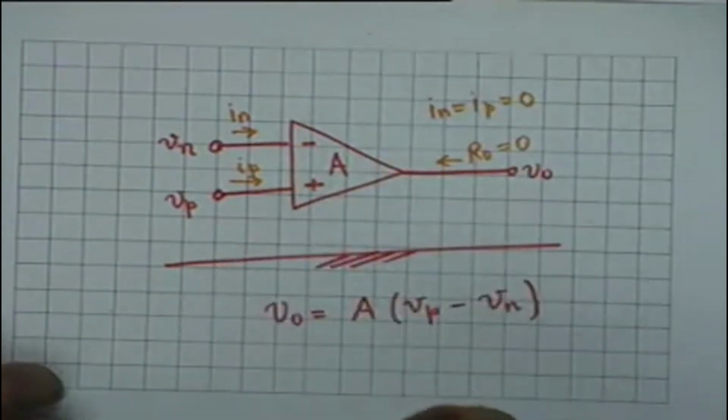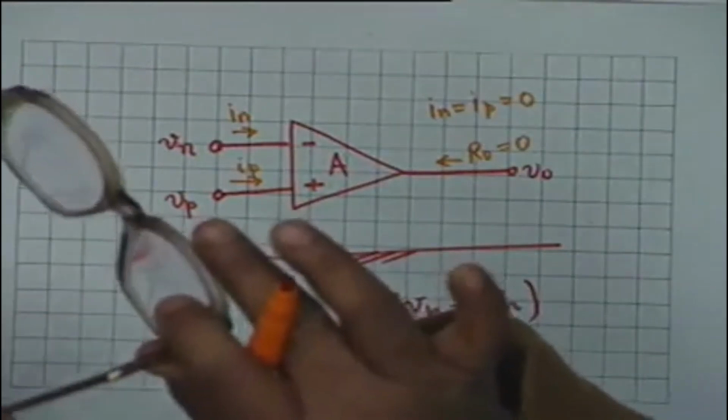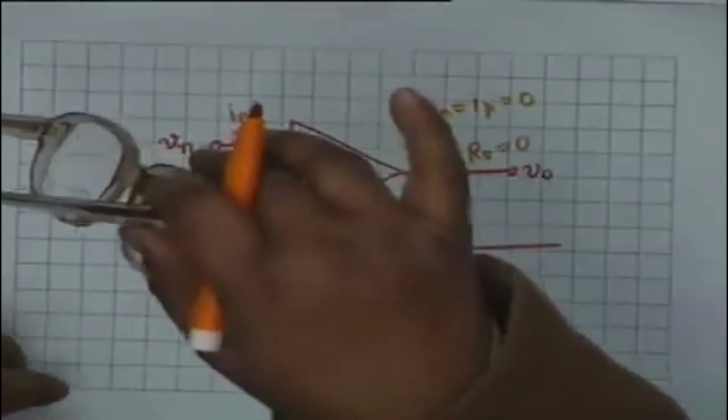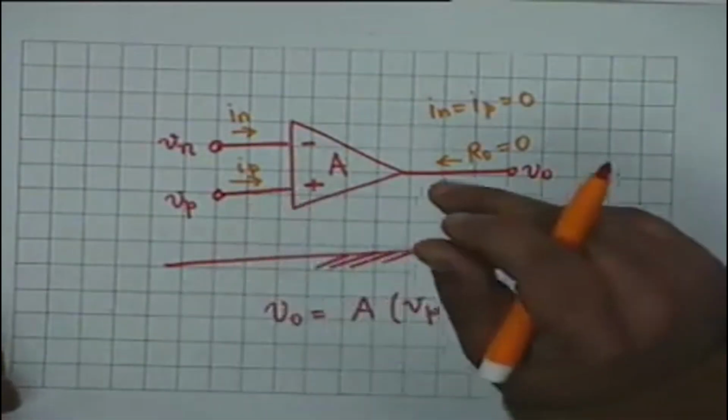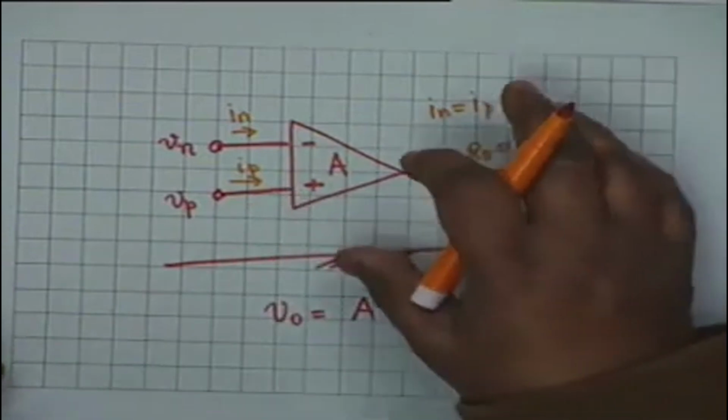These two batteries. Now you know that batteries have a limitation; they cannot supply more than a certain value of current. Therefore, ideal is ideal, but for the limited purposes of instrumentation and control, the ideal characteristics are almost always valid, and therefore we usually treat an op amp chip as ideal, unless it is a critical application where we shall have to look into the sources of non-idealness.